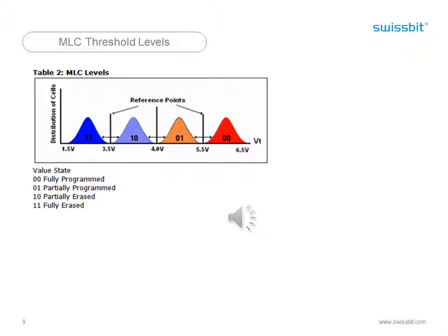In order for a flash cell to be considered MLC technology, the cell must exhibit two characteristics. 1. Precise charge placement. 2. Precise charge sensing. Thus, MLC flash works the same way as SLC flash, but the threshold voltage must be more precise to manipulate the state of the flash.